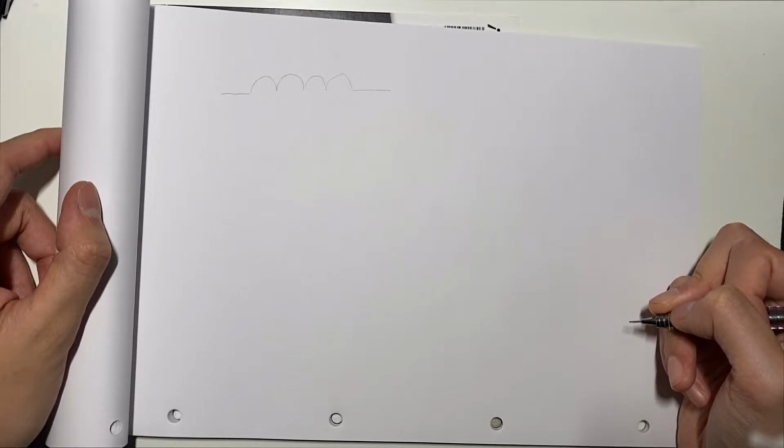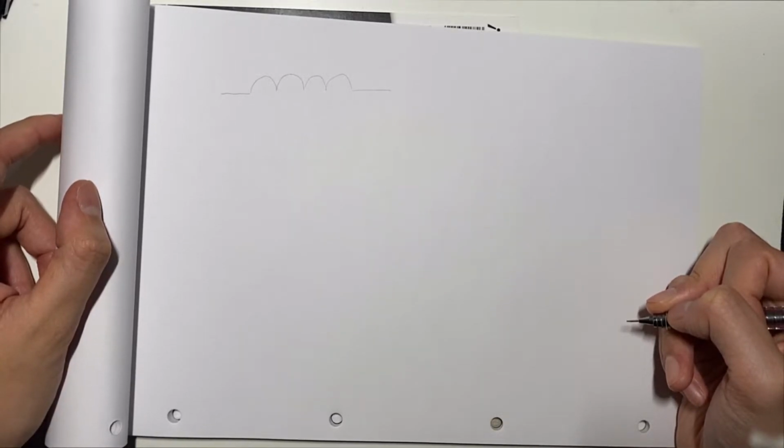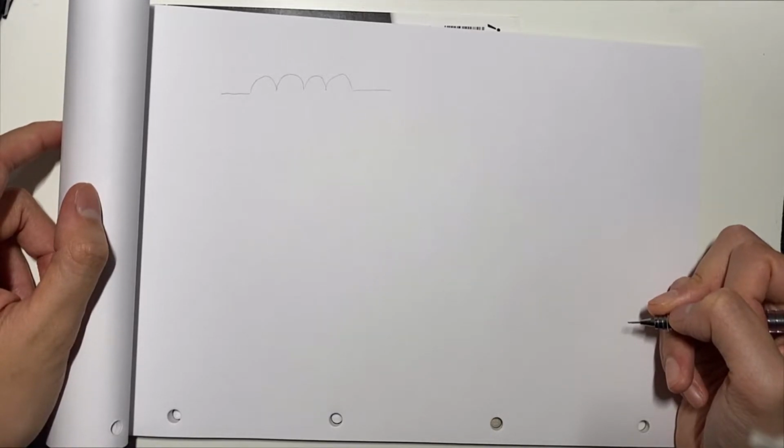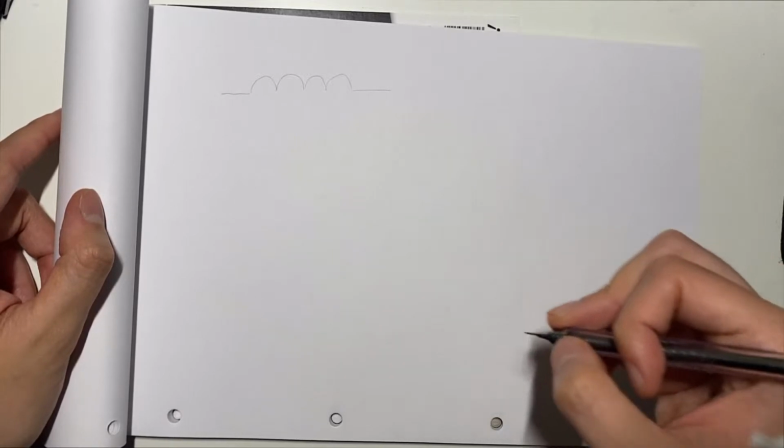If we change the current by increasing it or decreasing it, the magnetic flux around the coil changes, and this induces a voltage across the inductor. As we mentioned before, this voltage that we have just generated can cause a current to flow in the opposite direction of the main source of current. And this is otherwise known as self-inductance or inductance.